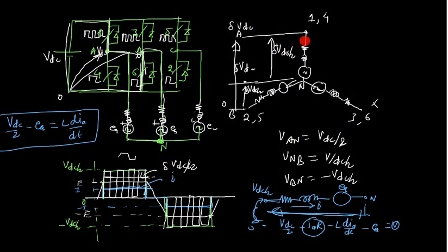Here you see. When you select only the switches, let's say we select switch 1 and 6 in a particular Hall state, so this was kept high and this was also kept high, meaning this is on and this is also on. The voltage which was appearing was only VDC voltage. Yes, and then half voltage will be across this phase and half voltage across this phase, VDC by 2, VDC by 2.